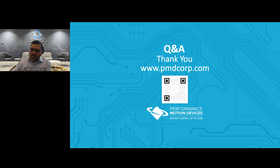So there's off-the-shelf planning software that can compute. If you look at the mobile robot in the warehouse, they have off-the-shelf mapping and planning software that would actually compute points. And what we provide on the drive or the chip is the capability of loading a table with 10, 20, 30 points. So we'll do the whole sequence of points, and we'll give you a status of where you are in that path. And that's very common because of the update rate: if you have to provide an updated position every segment, there's a lot of communication happening from the central controller to the slave.